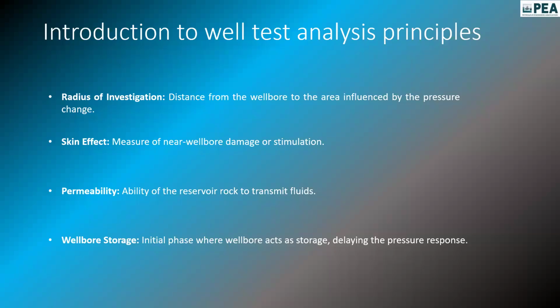Pressure will show high. At a certain time period, you can see an abnormal hike in pressure. This will be adjusted after some time. This abnormal hike shows that your well has been affected with wellbore damage. The fluid coming inside is not just crystal clear fluid, rather it is mixed with some debris. It could be either through the annulus or from the reservoir rock. All together it will be converted as wellbore storage. This part will be included in the crude oil and start coming into your well.